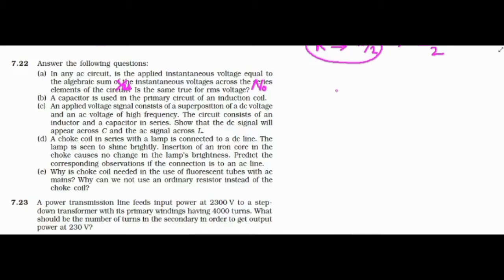We know that when you switch on the circuit, you can see a spark. What is the reason? Between two terminals, the air gets ionized and becomes conducting. So that's the reason electricity passes through the air at that time, and being a poor conductor, the air gets heated. That is why you see the spark. The same problem will happen here also. When you suddenly switch off the inductor, which is at a high voltage and current, the sudden disappearance of the current will produce a very large induced EMF, producing the spark.